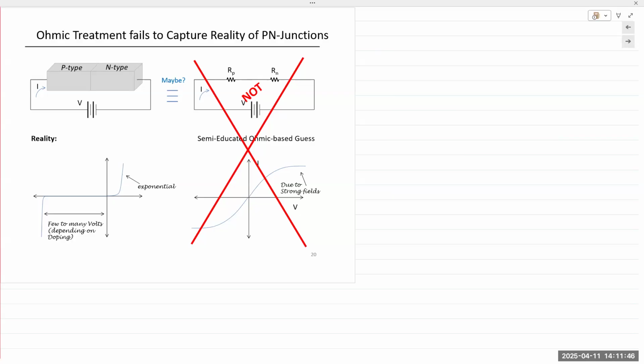But that's not actually what happens. The expectation would be that it might be linear, but when they first created these diodes and semiconductor devices, they discovered that the relationship between the voltage and the current was non-linear. It's evidenced here: this is positive voltage, positive current. They discovered that there was no current flow through these devices until the applied voltage reached a certain level.